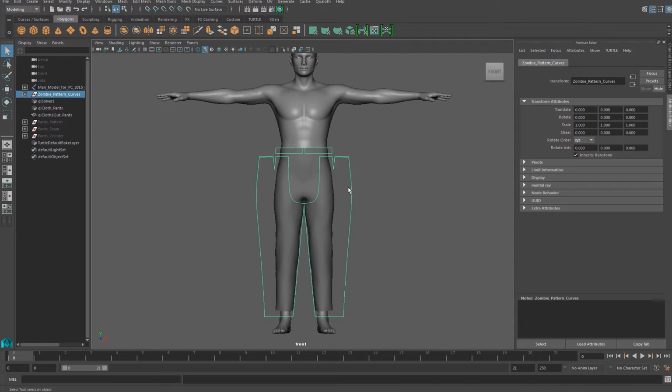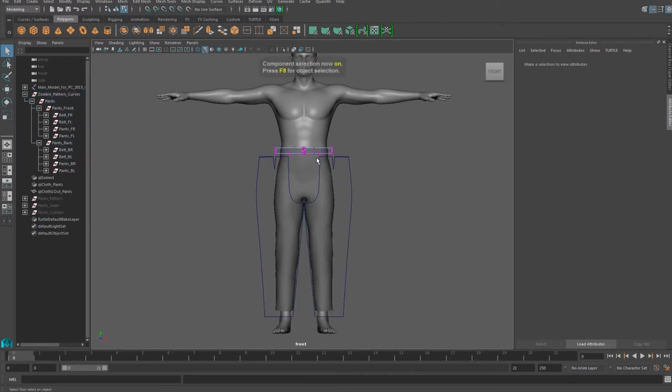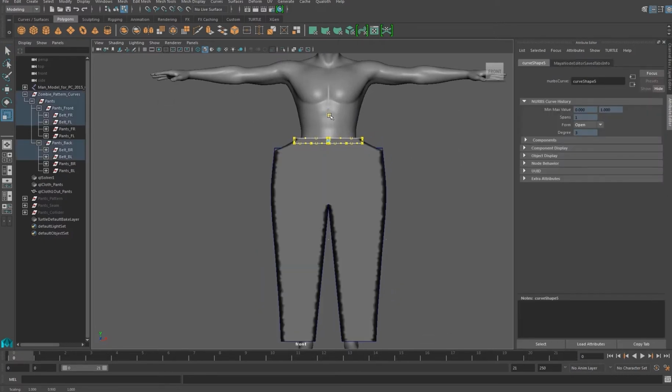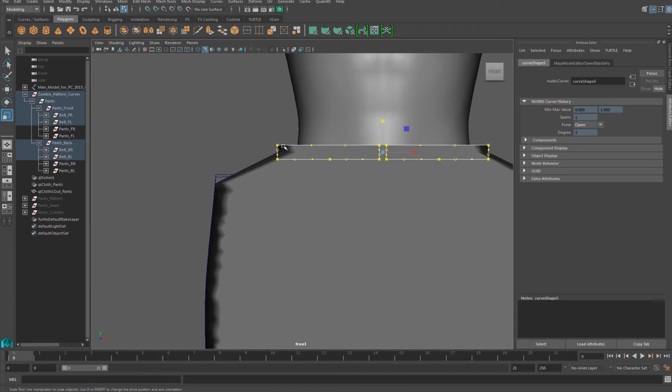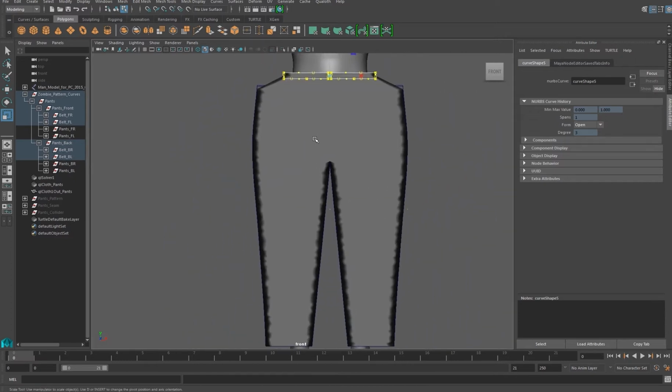If you're done deleting the constraint, select the required pattern curve group that needs some editing. Press F8 to change into component mode. Start editing the curve after you select the control vertex. Then the cloth will update the custom mesh automatically. Make sure snapped curves' endpoint and the begin point are not distant to each other. If you find the cloth is not draped properly during its simulation, make sure you check this part while draping. Then let's edit other pattern curves, make a new plane constraint, and begin the simulation to finish fitting the trouser.